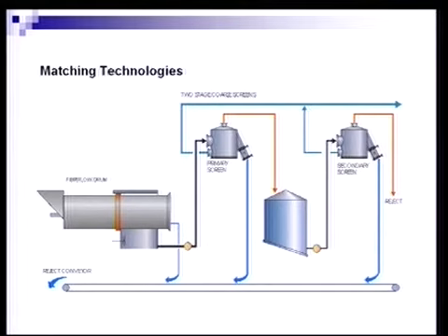Matching this technology with unique drum pulper technology has been found to be of an advantage, although many centripetal coarse screens are used in conjunction with low consistency continuous pulpers as well for the packaging grade processing of secondary fiber.